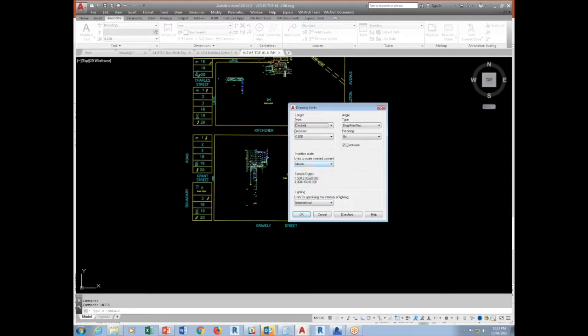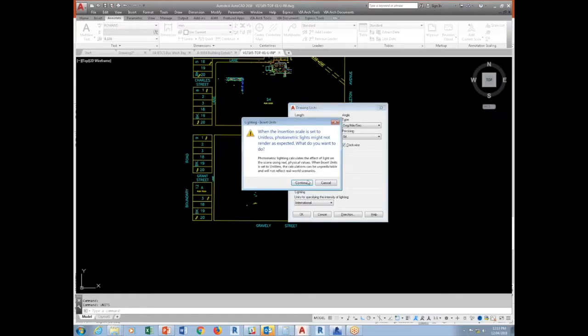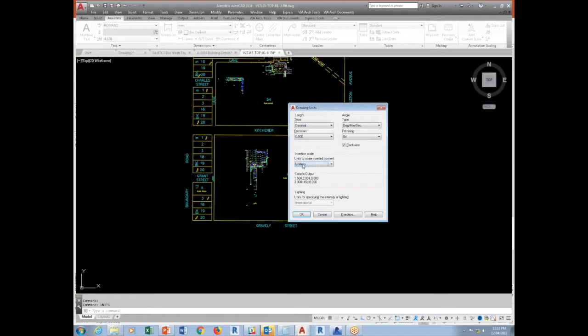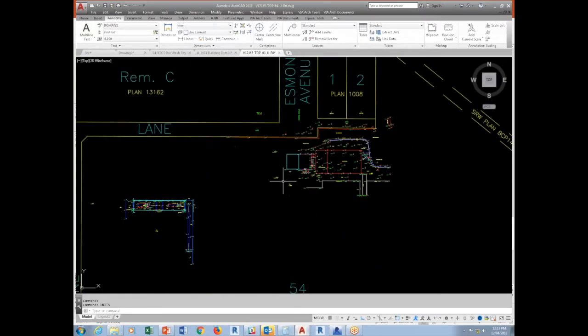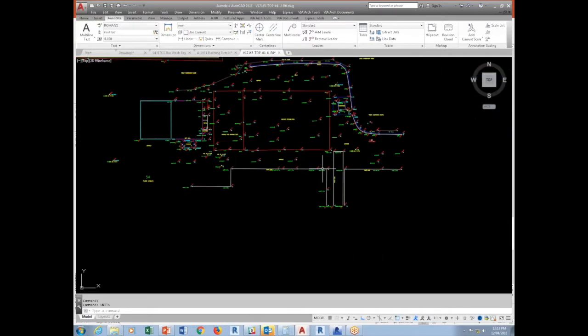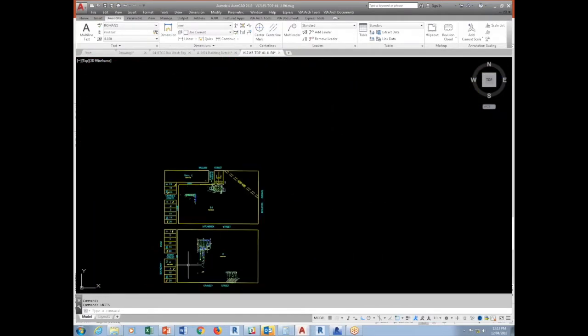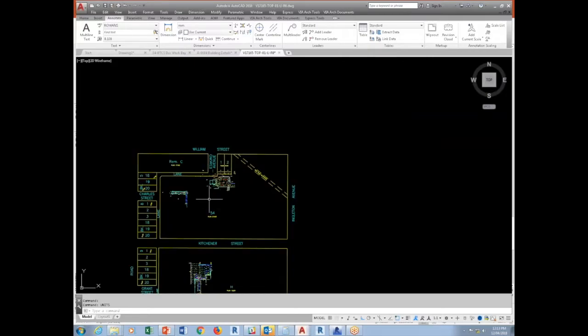They assume, oh, it's wrong, I have to scale everything. With the new version, I'll just say don't do that. First check what units they are. If it's set to unitless by default, the first thing you have to do is measure or use some sort of visual cue to determine whether it's meters or feet. It's very important that you try to find an object and check its distance. For example, this distance says 276. It could be 276 feet or it could be 276 meters.